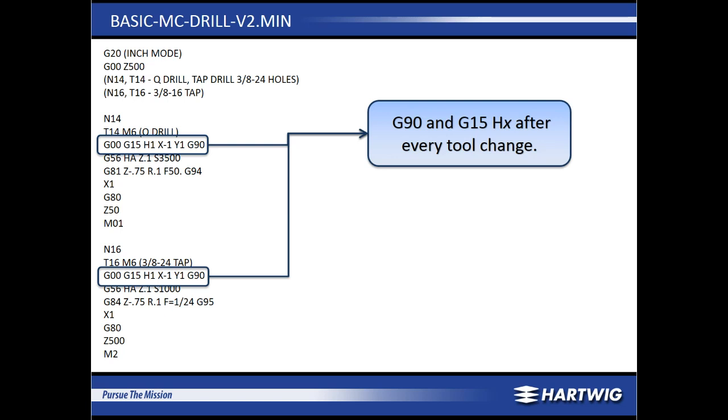So I would position a tool to where I wanted it to be at the start of a tool path, then I would have a subprogram that moves everything inside of it incrementally. But if I was to hit reset, or if I was to forget to come back out of incremental mode whenever I go back into my program, I could have issues with my positions not being where I wanted them to if I was to stay in incremental mode whenever I wanted to be in absolute mode. So we just like that being there to make absolute sure we're in absolute mode.